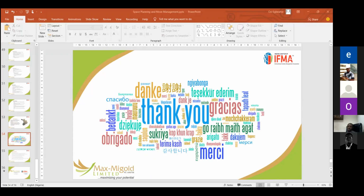will go from the ground floor to the 20th floor to maintain a split unit air conditioner. It is costing 200,000 naira, and to erect that scaffold will almost cost you maybe 800,000 naira. So you can discover that it is difficult to maintain. So normally at such levels, you don't use split units. You use chiller systems or you use VRF or VRV for the cooling system. That's why those technologies are there, because it's easier for you.